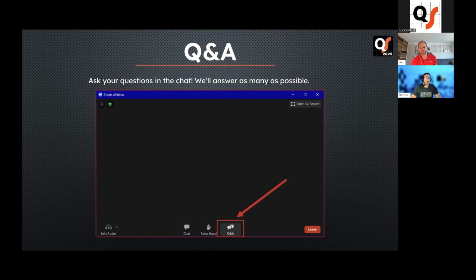So if you have a bolt hole or a shaft or something where you have to have a specific size, I would not rely solely on the mesh because the mesh is going to be very subjective to surface finish, ambient lighting, how many points were captured, how it was processed.